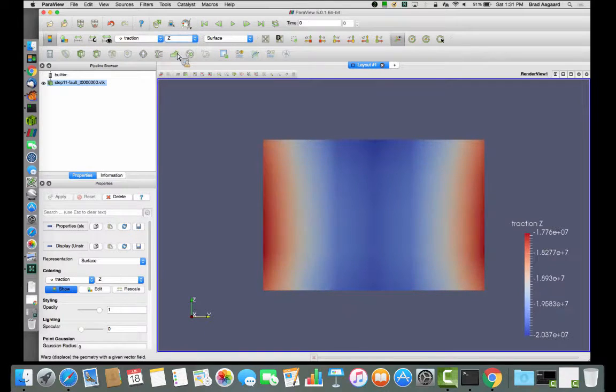So our normal tractions, because we have free surfaces at the boundaries of the box, remember we grabbed the box and basically sheared it where the y boundaries are free surfaces. When we shear it, just moving parallel displacements in these free surfaces, the normal stresses at those ends, as you can see here, are less than the normal stress in the middle. So that creates a difference in traction. Here is the traction, so bigger tractions in the middle than at the edges, corresponding to these normal stresses.